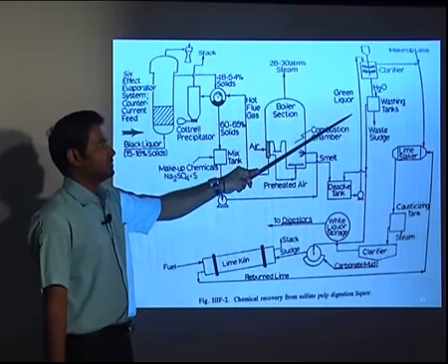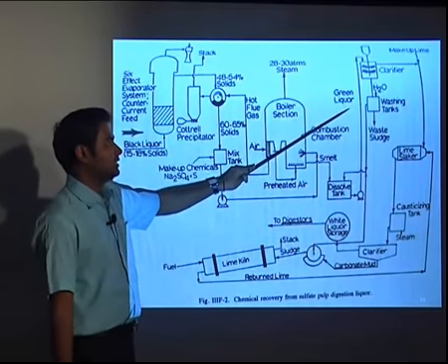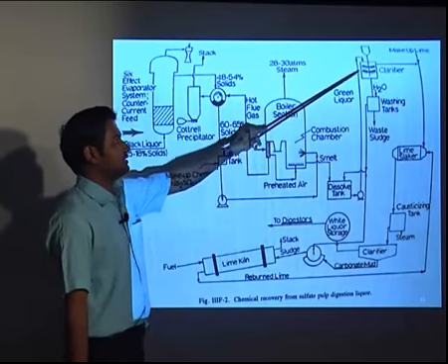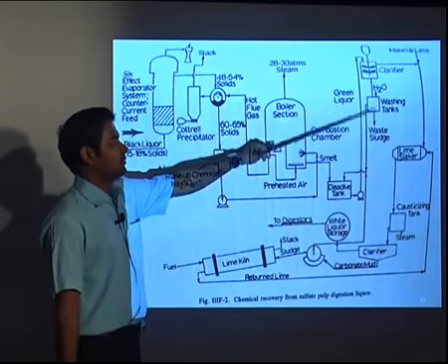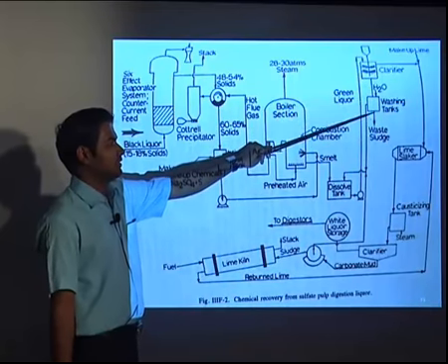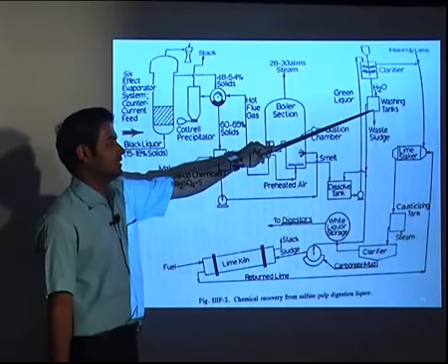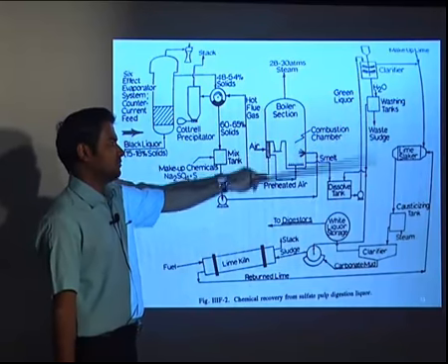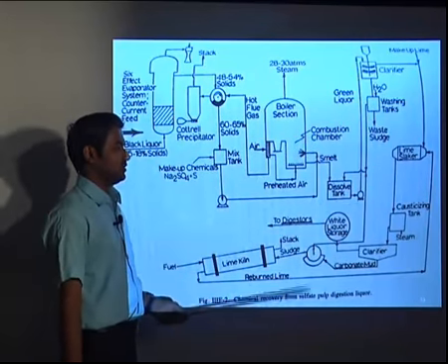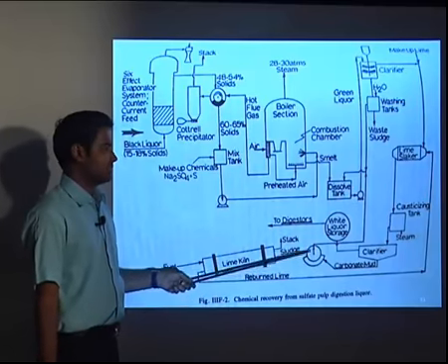Green liquor, because it will have a low percentage of the harmful chemicals, and it is sent to the clarifier where the chemicals will be removed, and whatever solid we get over here will be sent as the waste sludge. Whereas the other chemicals will be recirculated in order to get back the more chemicals required.